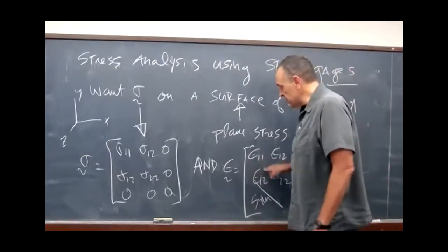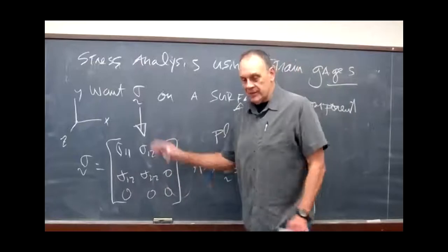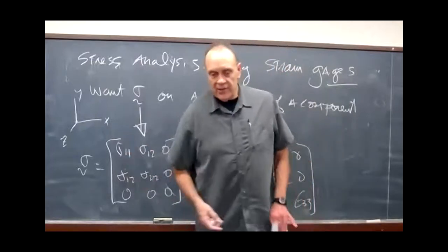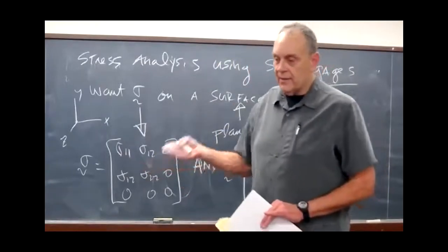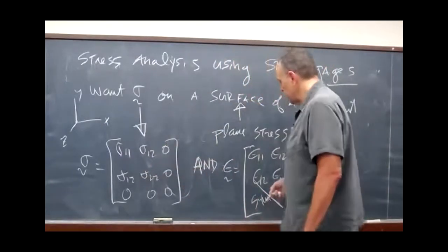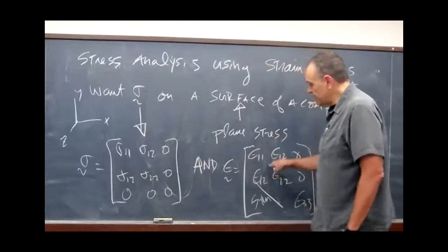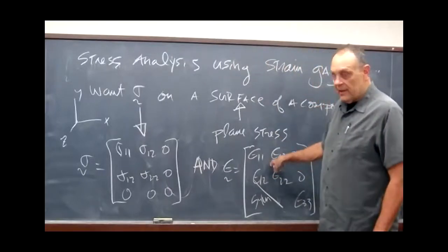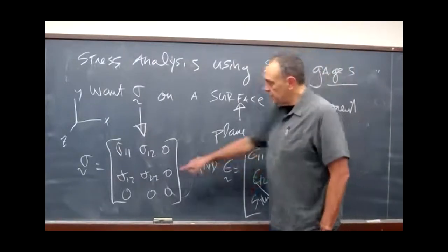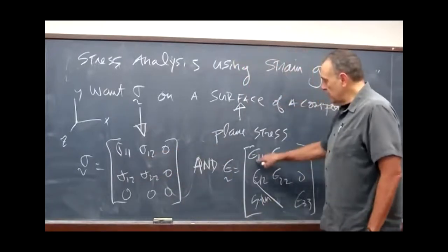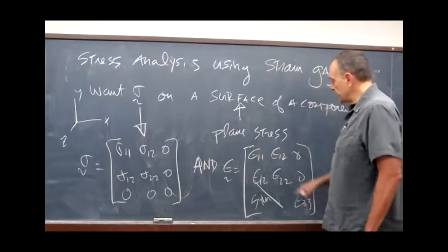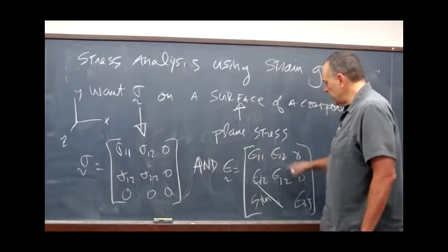In our business, we measure strain and compute stress. In everybody's business, people doing tension tests with a load cell are measuring strain and converting that to stress. So the idea is I want to measure this strain tensor, and I want to compute the stress tensor. I need to measure these components of strain, epsilon 1,1, epsilon 2,2, and epsilon 1,2.